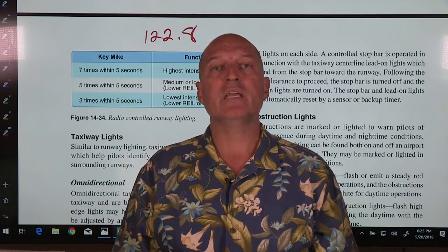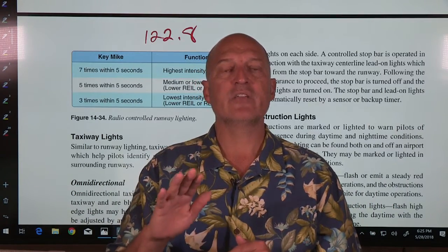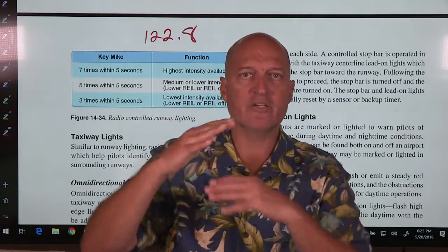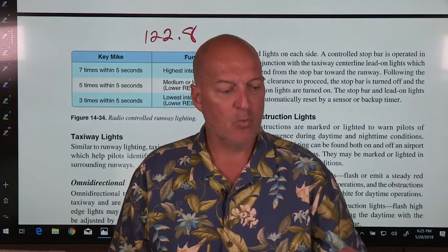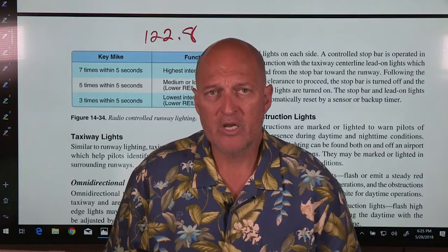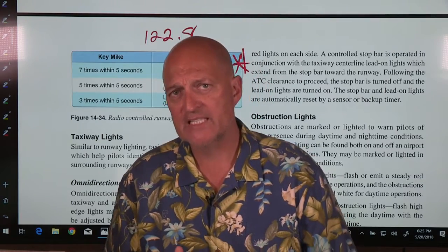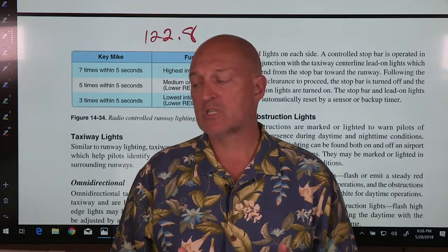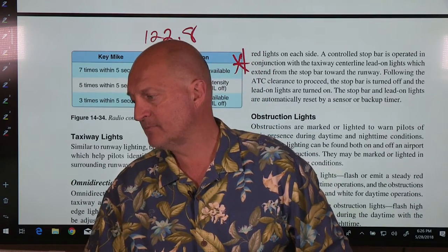And the reason being is so that you don't try to flare the airplane and land that sucker before you get to the runway. So that's what we normally teach when we are teaching how to use the lights for that runway. So that's what PCL, or pilot controlled lighting, is all about. Okay?